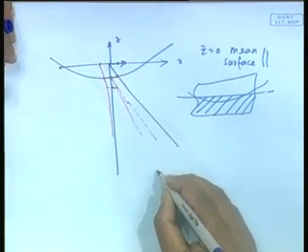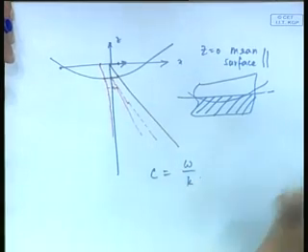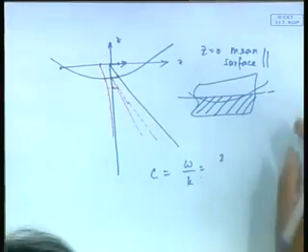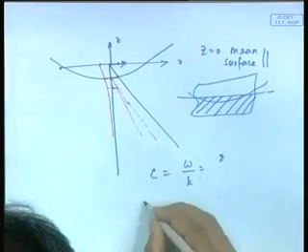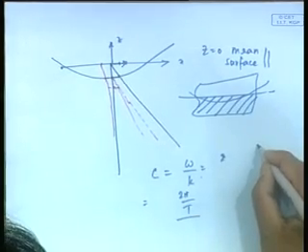We will discuss the other aspects of energy, energy flux, group speed, etc., and perhaps we will also work out some simple elementary calculations, how these numbers are used to determine. You can actually see from here itself, as an example, this speed, as I said, c is equal to omega by k, and omega square is gk.